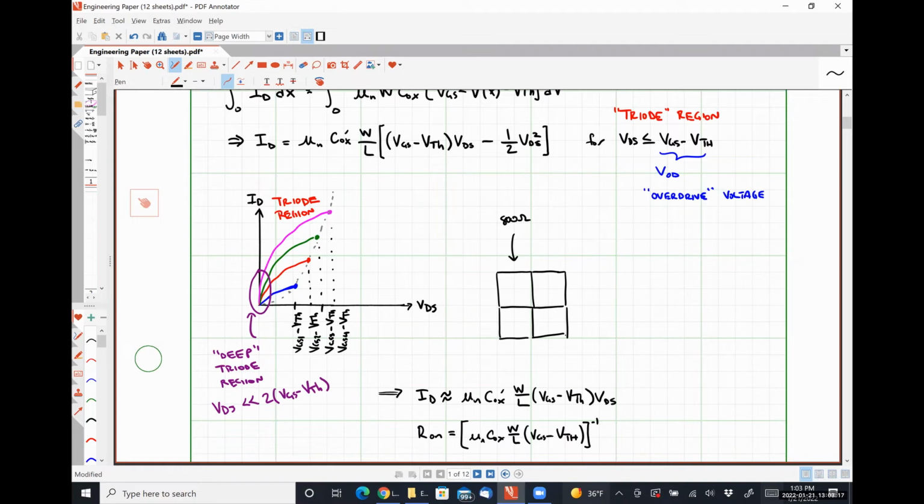The resistance of a MOSFET transistor is tunable depending on what our voltages and things like that are. So we can very often achieve comparable resistances to an N-well resistor or a high Z poly resistor with a small transistor utilizing much less space. To get really large resistor values is going to be hard here, because resistance is effectively going to be voltage over current, right?